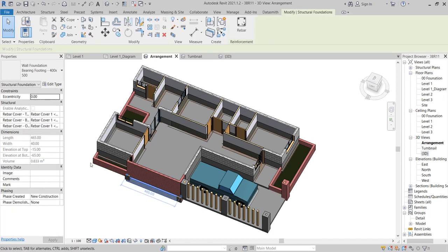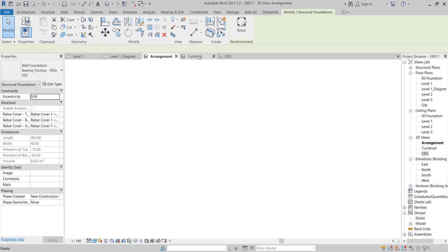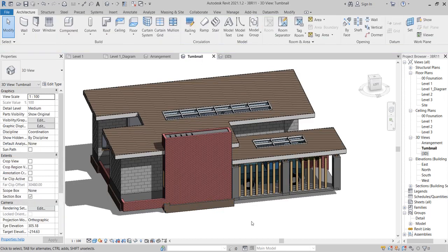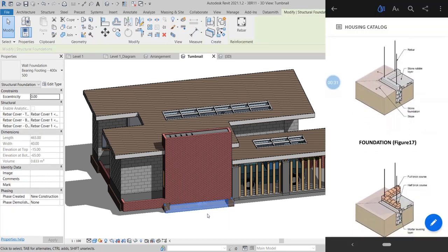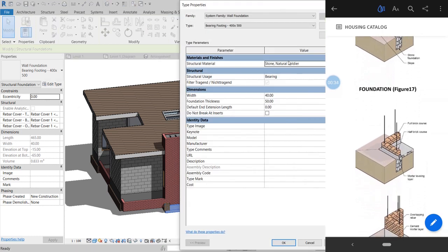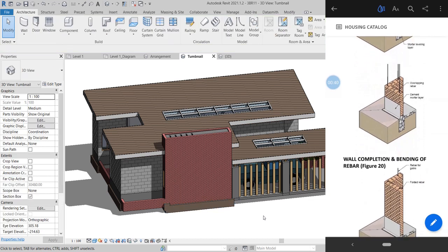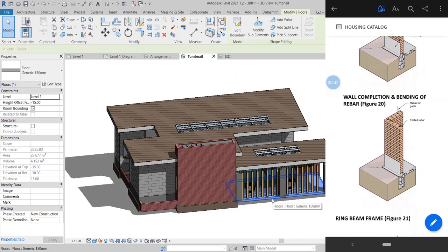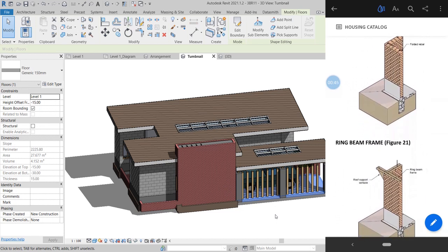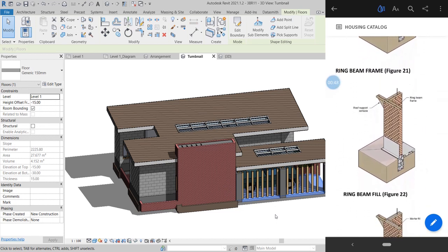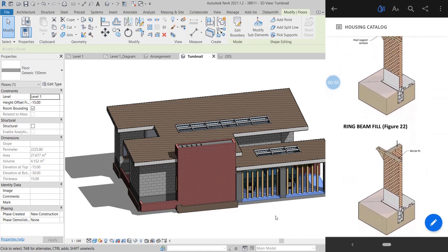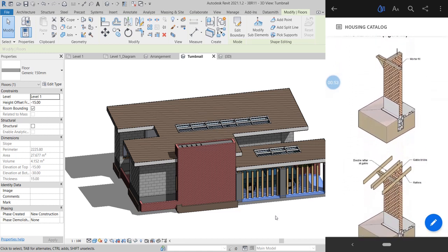Now let's talk about materials and structures. Let's go to this diagram here. In most of the cases, I try to use locally available material as much as possible. Now, the foundation is made of natural stone. As you can see when I go to detail, it is natural stone soldier, and the floor is actually generic. By generic, I mean the concrete, the stone aggregates with the cement layer on the top.